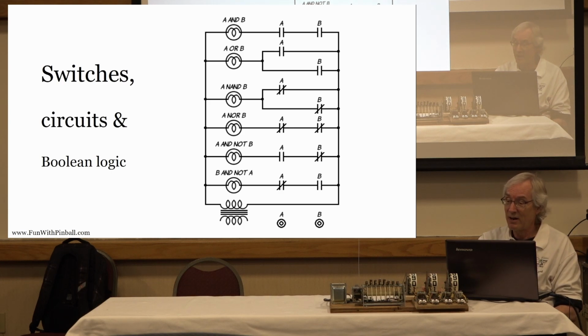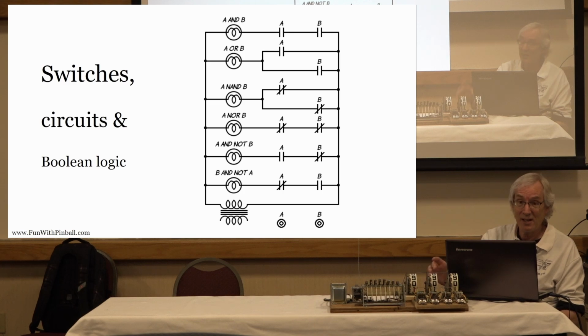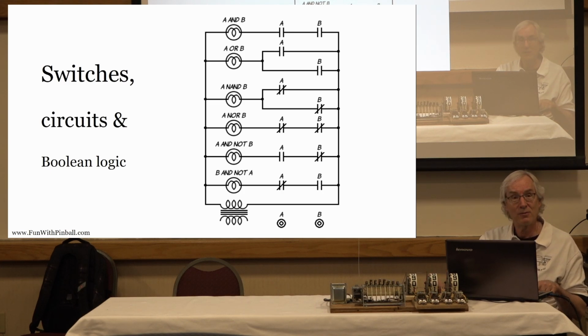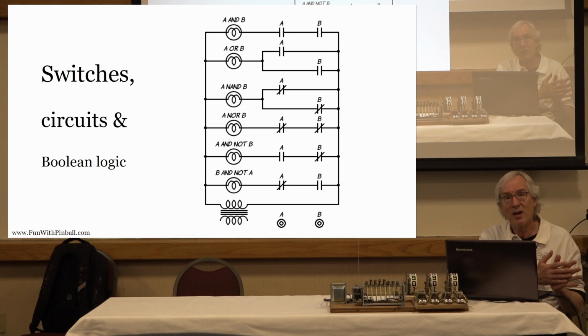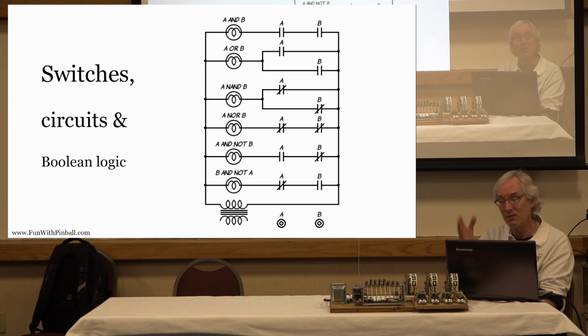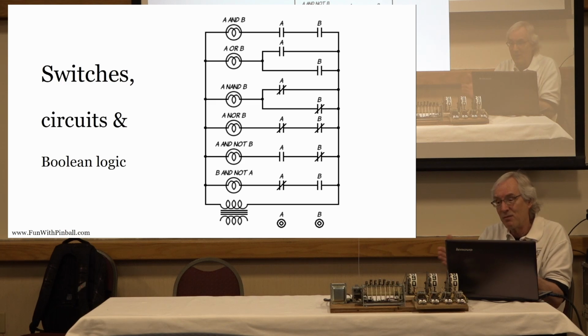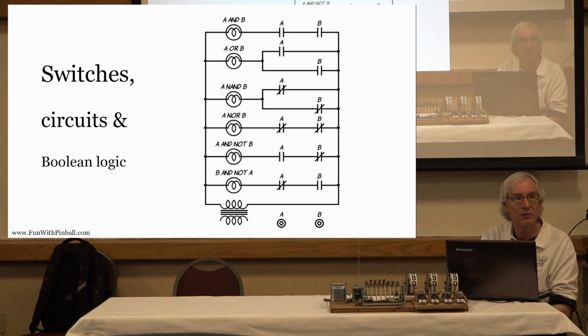If it doesn't fire, the problem is not my score reel. The problem is my relay, right? If my relay does fire, well, I know that the target can talk to the relay, so I can eliminate half of my problem and now focus, why don't I get from the relay to the score reel, right? You divide the problem in 2 and see if you can isolate one from the other, and keep dividing by 2 until you figure out what the issue is.